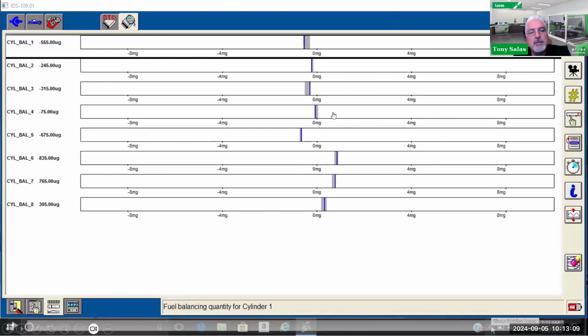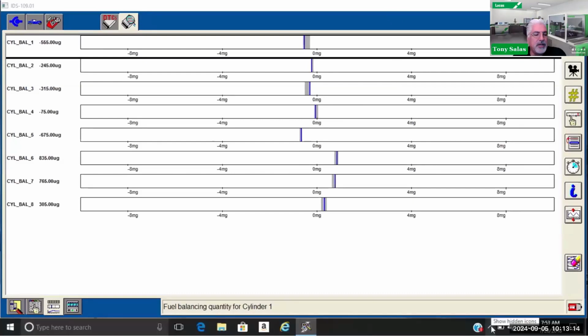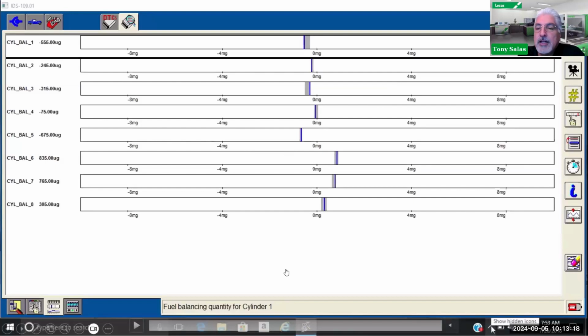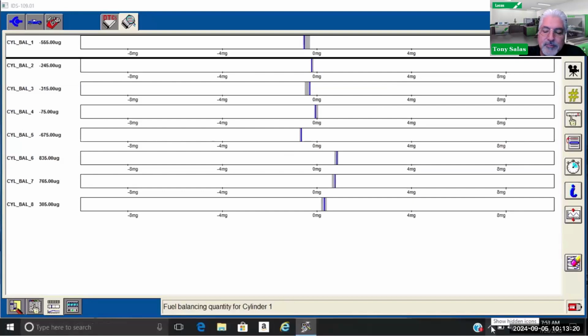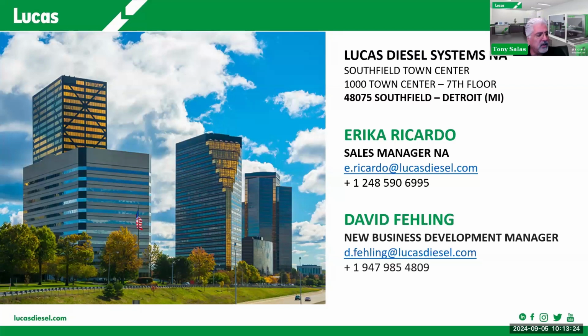But if you see one of them sticking out more than the others, that definitely is a red flag that you probably have injector nozzle issues, which again, you can run a cleaner to fix, unless you've got low compression. But then on this Ford product, you can run a relative compression test.